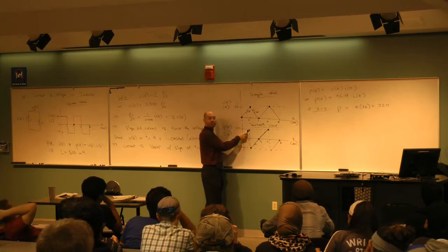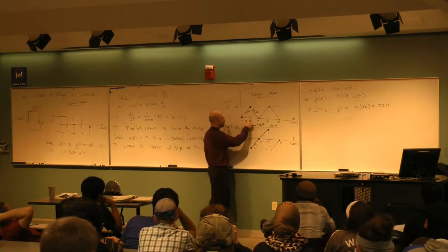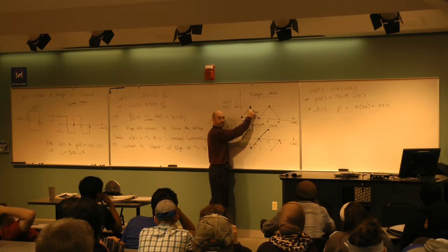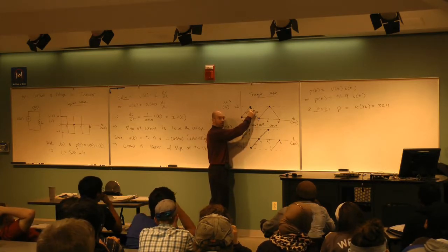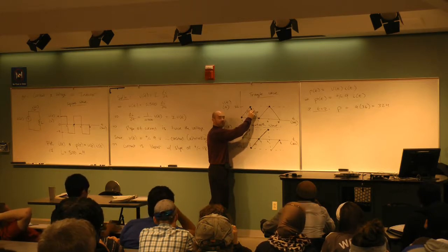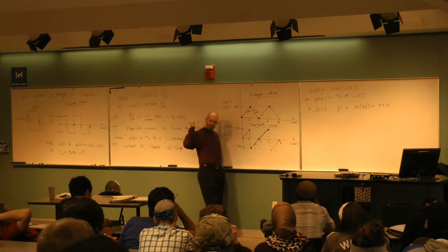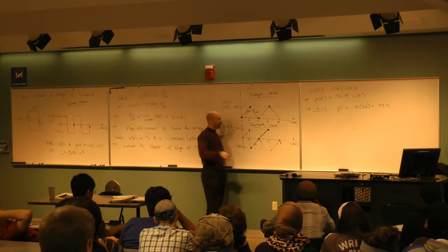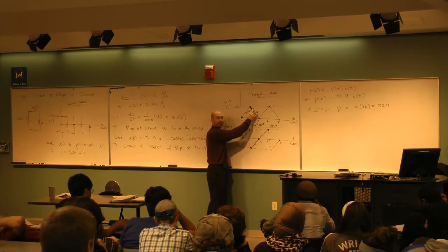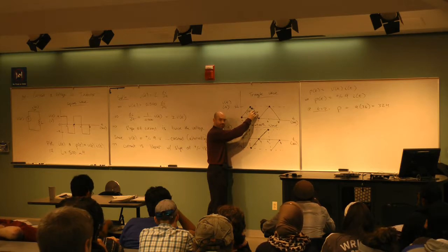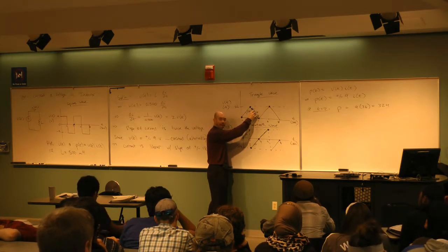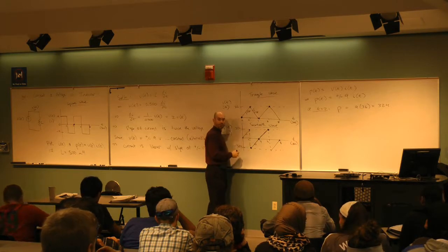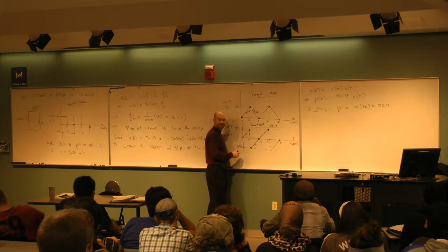That gives me this. Now as soon as I'm between 2 and 4, I know what the current is, it looks like that. And the answer for the power is the voltage times this line. Well, if I look at the voltage between 2 and 4, the voltage is now a negative number. So I need to take this line and multiply this line by a negative number. The easiest way to multiply a line by a negative number is to take the two endpoints of the line, multiply those two numbers, and connect the dots.